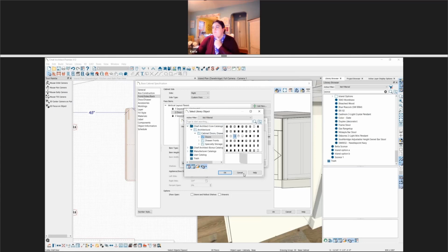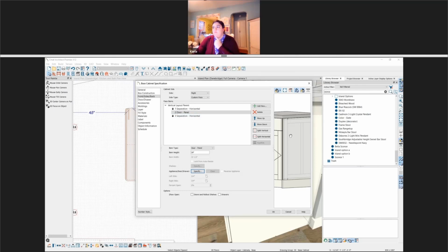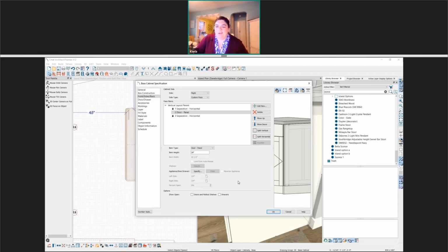Does that add to the width of the cabinet? That one does, because this full cabinet is set to be a full overlay. If the cabinet in general was set to be an inset, then it would not. Can you offset that panel, like say -3/4 of an inch somehow, so it's integrated? Not in the way you're describing. I don't think so.